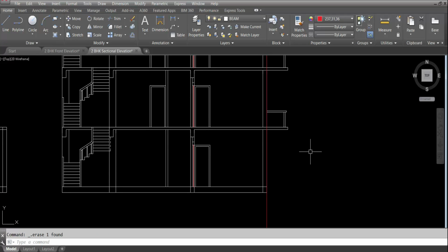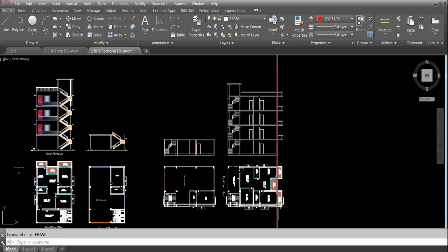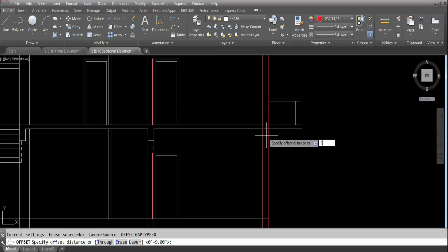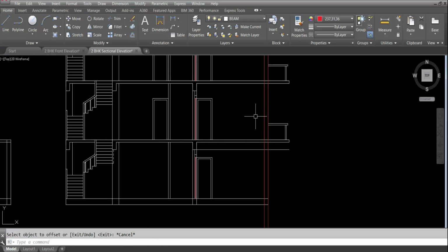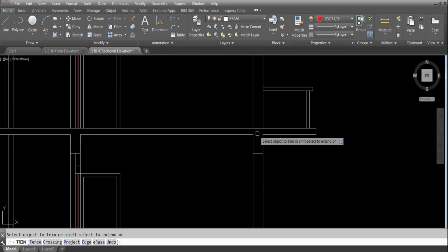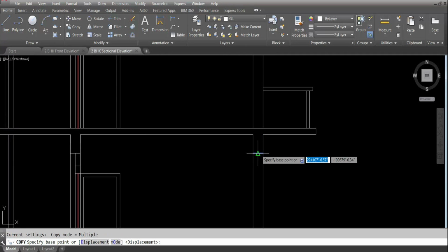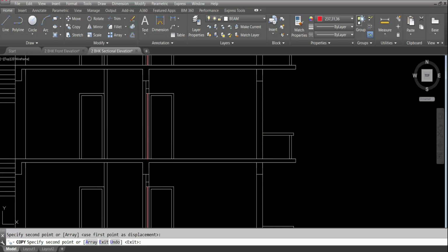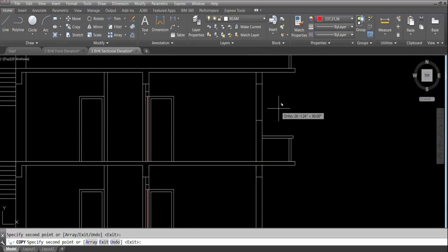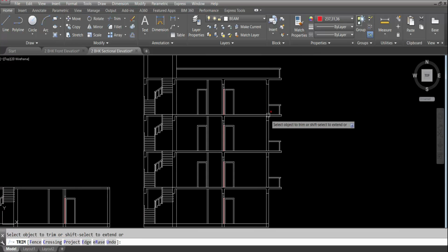Alright, now take, this is on this wall, see. So we have to provide beam here, offset distance 15 inch. Select this line and click to downward direction and trim all the extra lines. First, trim these two lines and delete these two construction lines. This is the beam and trim the roof slab. This line, extra line. Copy this line, paste it here and paste it here and paste it here. Trim roof slab extra lines. Trim here. Trim here.